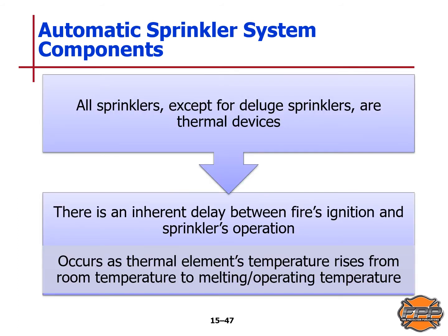All sprinklers, except for deluge sprinklers, are thermal devices. There is an inherent delay between the fire's ignition and the sprinkler's operation. This occurs as the thermal element's temperature rises from room temperature to a melting or operating temperature.